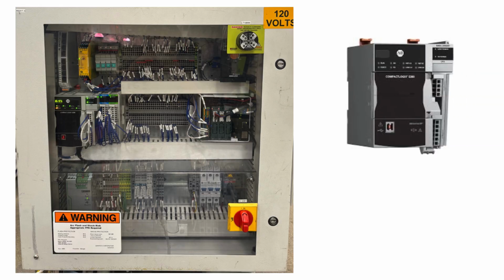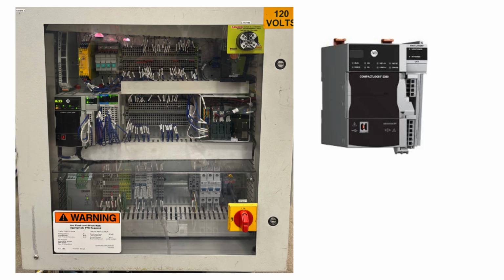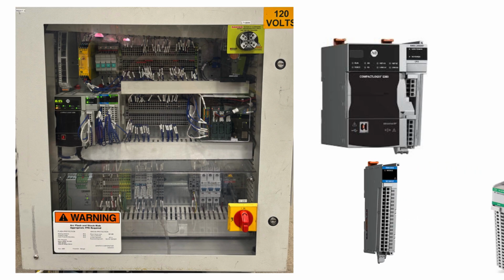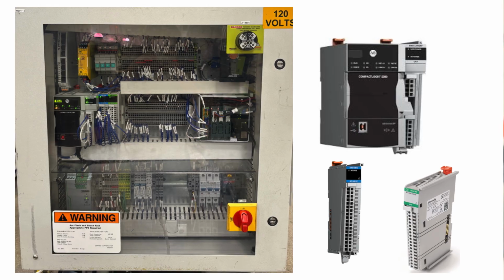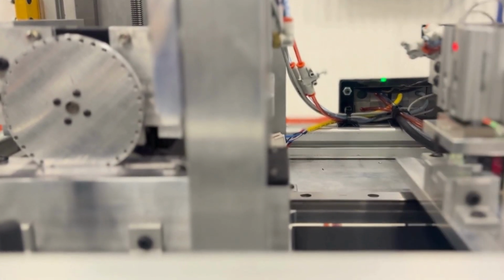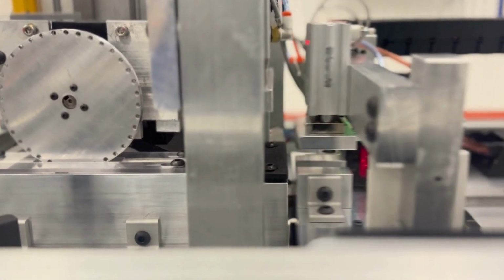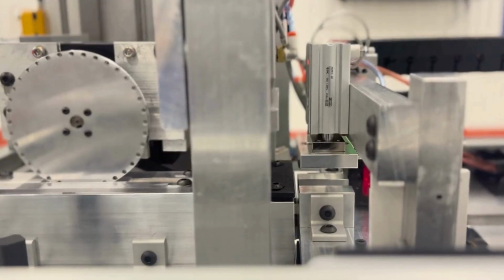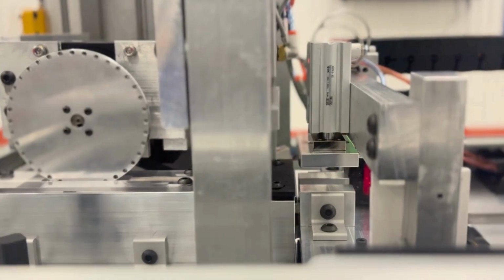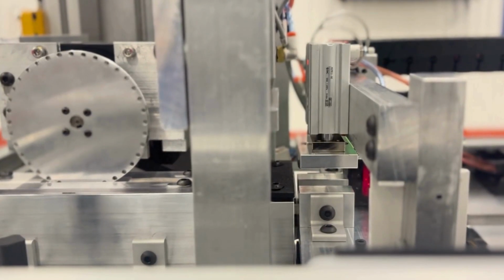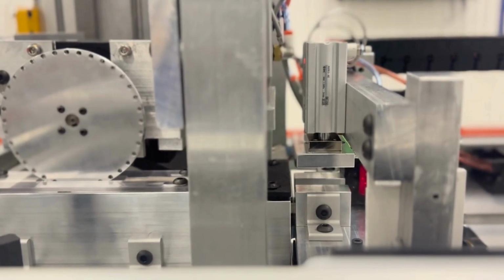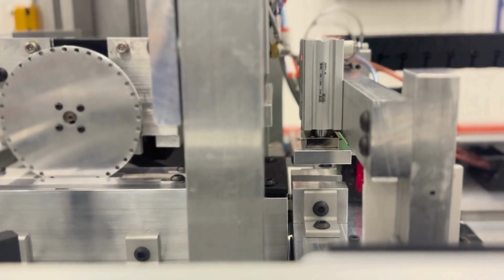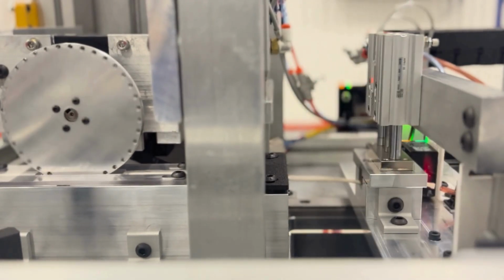The main system controller is an Allen Bradley CompactLogix 5069 PLC paired with Allen Bradley Compact 5000 digital input and output modules. The PLC executes a state-based ladder logic program. The process starts with homing to establish a zero point for the electric linear servo. The motion timing, the sensor feedback loops, and the pneumatic solenoid actuations are coordinated through the PLC to ensure consistent operation. In testing, the control architecture reduced our cycle time down to a rapid 6.12 seconds, far faster than the 20-second specification requirement.